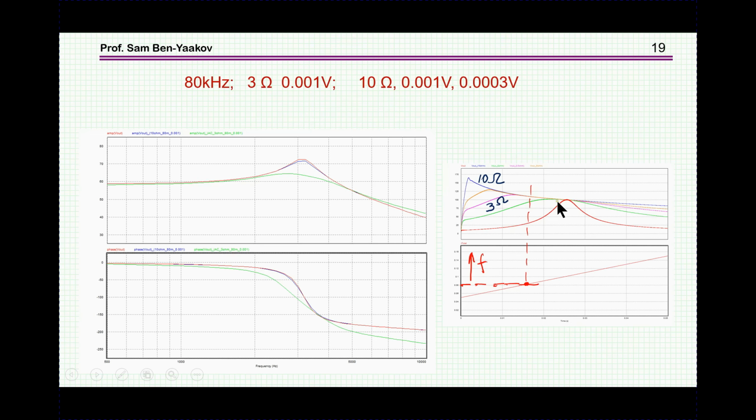This is the nice thing about the LLC converter, that it has a sort of constant gain here for a range of loads. So the slope is about here, but this is again for the very low frequency. So indeed, at low frequency, we see these two curves are just about the same. But as you go to a higher frequency, you see the effect of the reactive elements, the inductors and capacitor, etc., and this is why you see this region here. This is now the phase, and this is the amplitude.